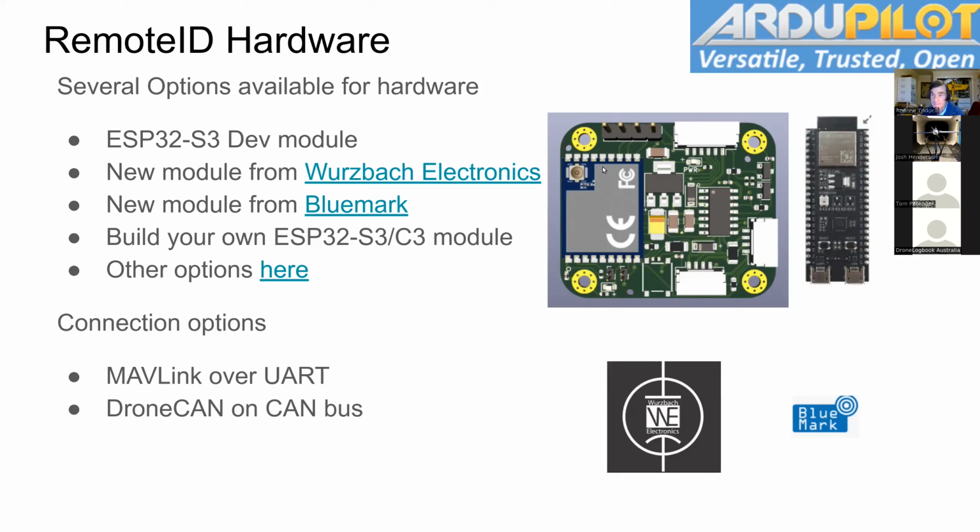I'm sorry, another question. If you're going to use the DroneCAN solution or the CAN bus solution, then you have to have a CAN transceiver. Any off-the-shelf CAN transceiver will work, or is there a specific one? It's 1 megabit BxCAN. I just got one off eBay that I use. I would expect that any 1 megabit capable CAN transceiver will work. The particular one I have on my desk is the eBay CJMCU-105, but I would be very surprised if you couldn't basically get any CAN transceiver and make it work. And so, yes, you'll need a CAN transceiver.